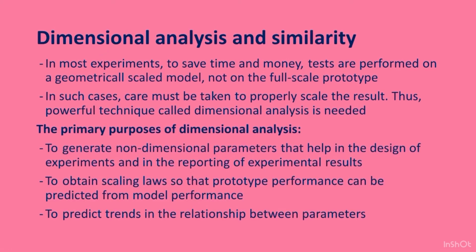Dimensional analysis and similarity. In most experiments, to save time and money, tests are performed on a geometrical scale model, not on the full-scale prototypes. In such cases, care must be taken to properly scale the result. A powerful technique called dimensional analysis is needed.